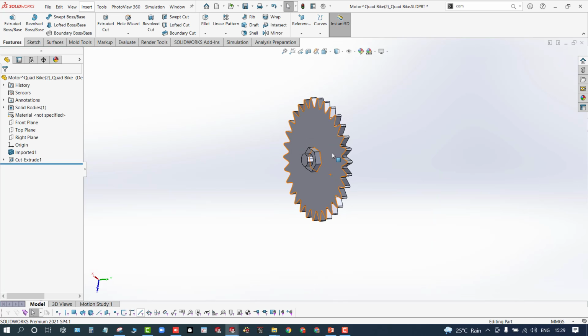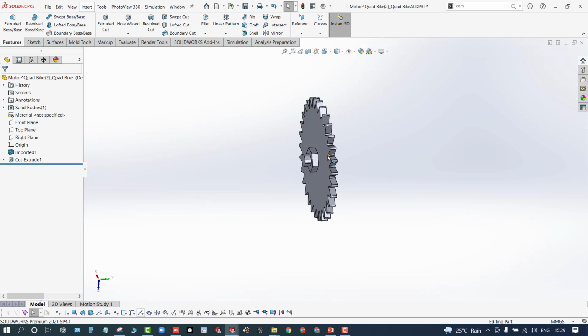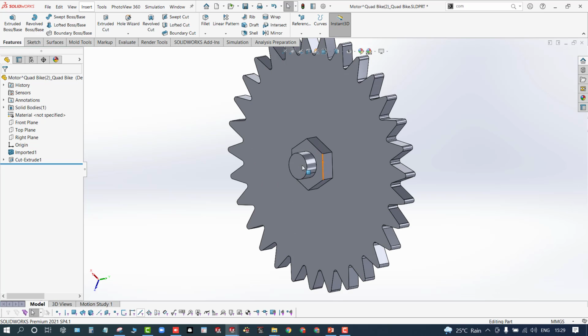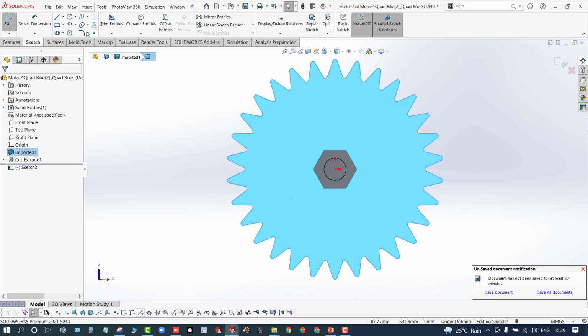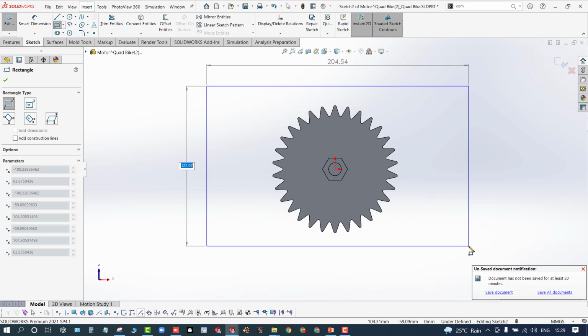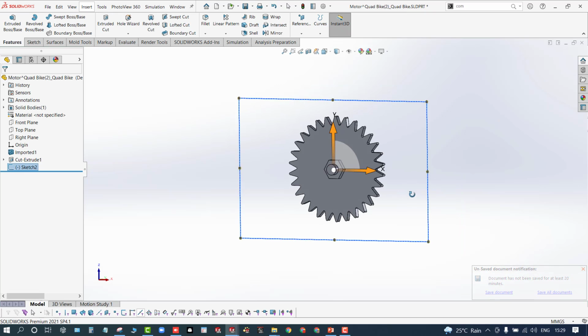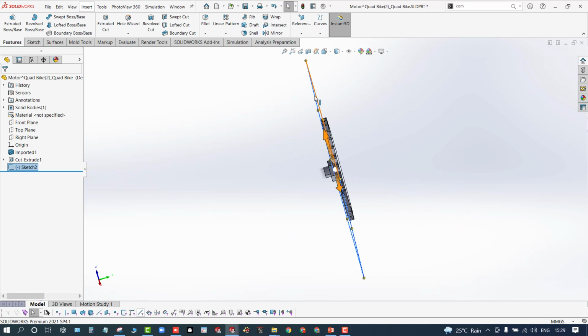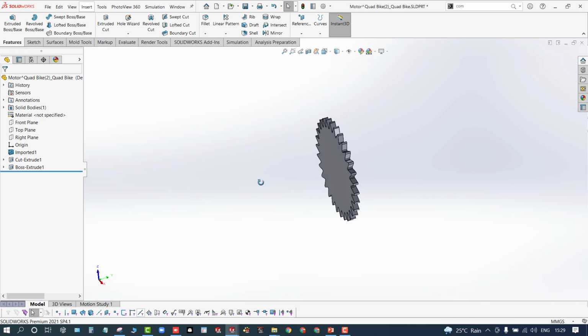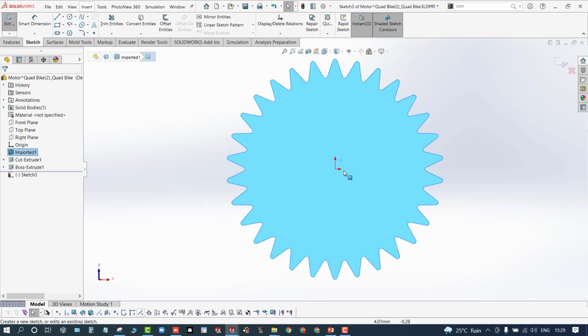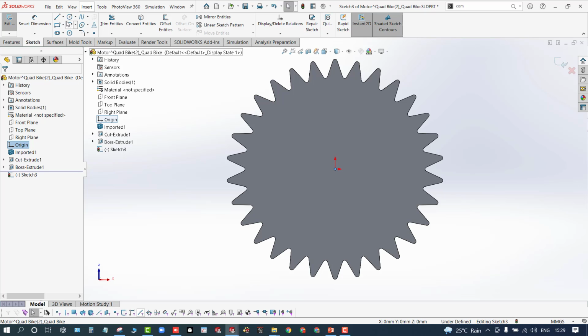Okay, even I don't need this part, this side one, but I need this diameter in reference. It is 5 mm radius, meaning 10 mm diameter. On this side also I'll do the same. You can use the 3D tool also to remove these. At the center I need a circle of diameter 10.